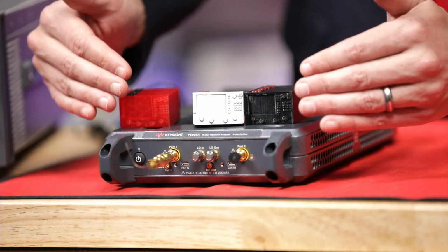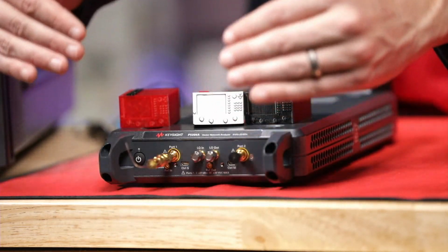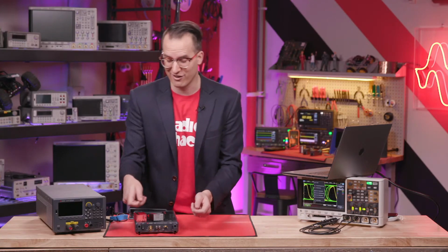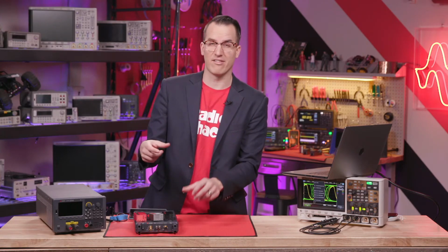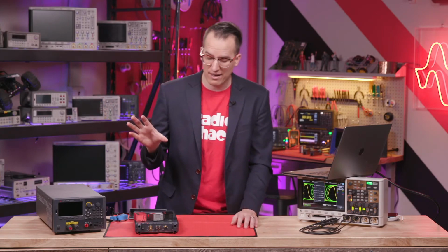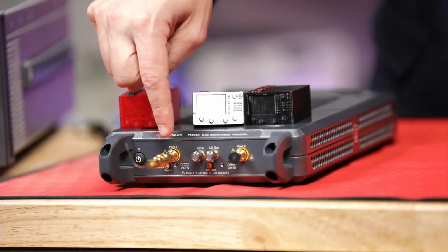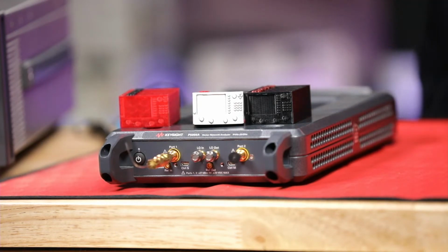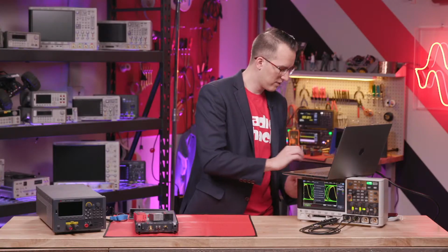So your calibration plane is essentially calibrating everything up to the point of your DUT, and your calibration plane is there right before your DUT, so that you're only seeing the effects of your device under test and not your cabling and your adapters and all that, because especially with a 20 gigahertz or higher VNA like this, you're going to see effects from your adapters and from any cabling you add in place. That's why in the video today, measuring a paperclip antenna, when I added my female-to-female adapter there, the Smith chart actually, you could see it going between open and short because the adapter was having some effect on the final measurement.